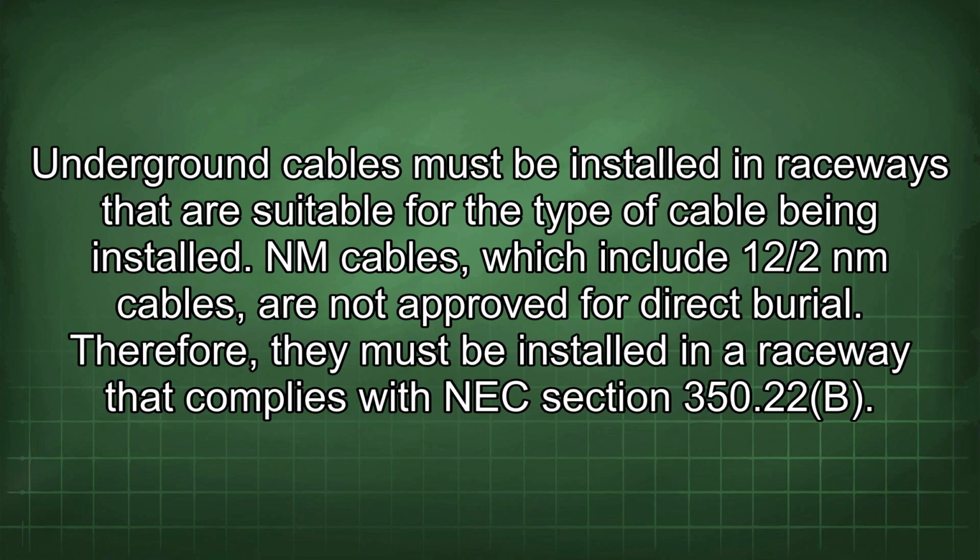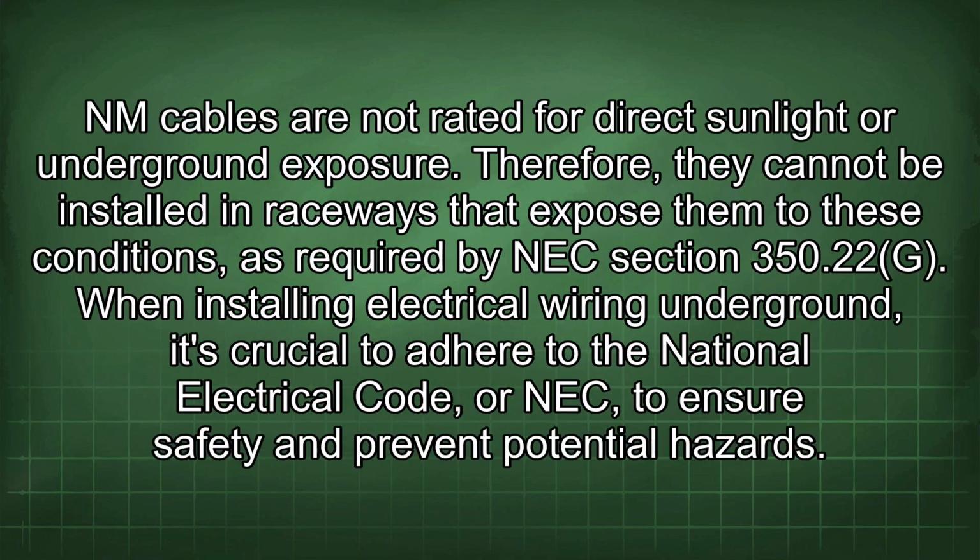NM cables, which include 12/2 NM cables, are not approved for direct burial. Therefore, they must be installed in a raceway that complies with NEC Section 350.22b. NM cables are not rated for direct sunlight or underground exposure. Therefore, they cannot be installed in raceways that expose them to these conditions, as required by NEC Section